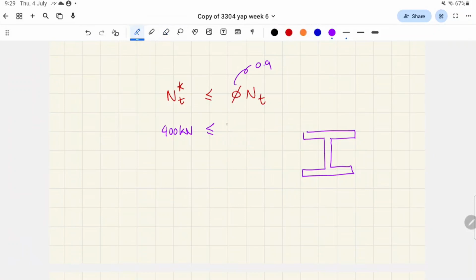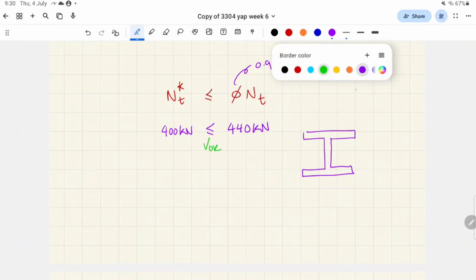The other thing that might happen is you might oversize it by too much. Say you oversize it and it's 550 kilonewtons on the right hand side, and you're wasting a lot of material, right? So essentially you're trying to edge it to be within an acceptable margin over, so that it's safe but not over engineered and wasting materials. That's what this whole capacity check is for, right? And if it passes this, it's considered designed correctly to AS 3600, right?